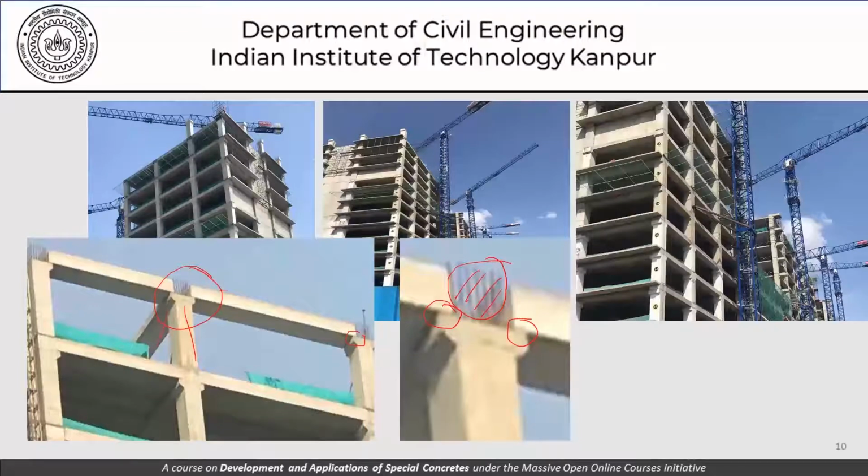These members are still reasonably vulnerable for displacements, and that sometimes becomes the cause for accidents when these precast members are placed in position but not securely fastened. So there have to be arrangements made for temporary fastening of these members while the permanent solution or the permanent steps to be taken as part of the overall construction are done later on.